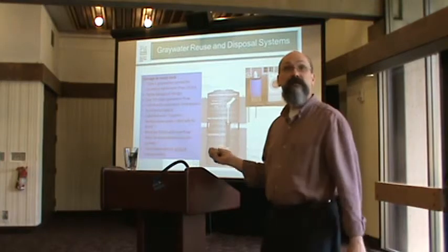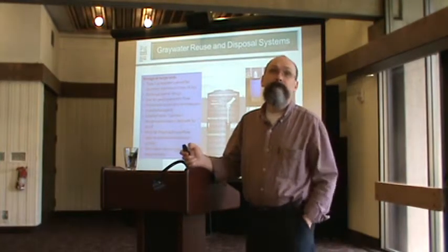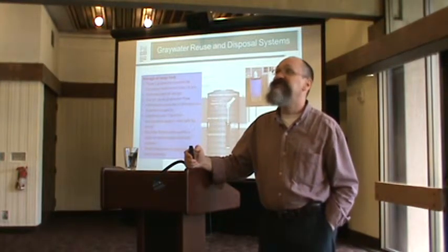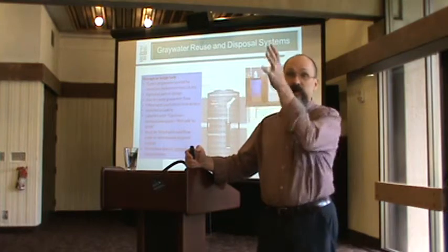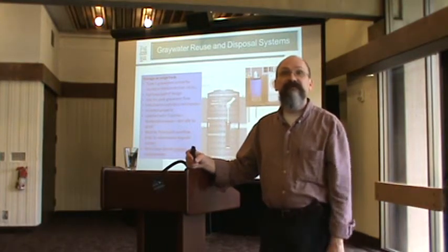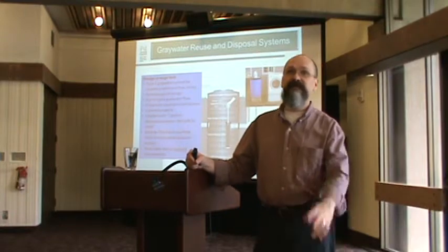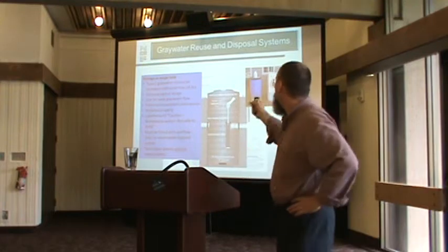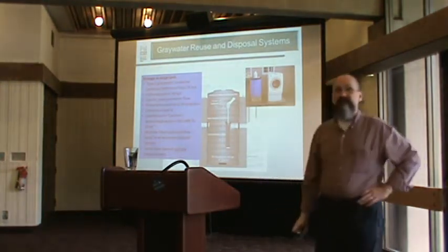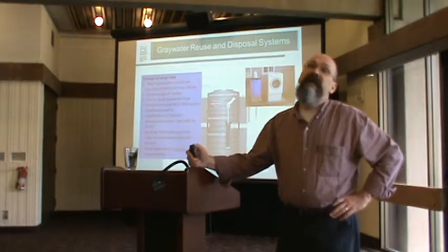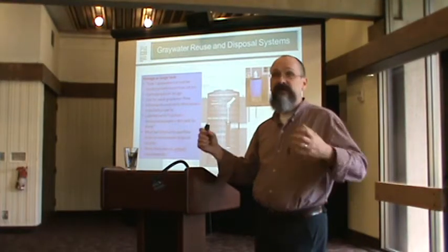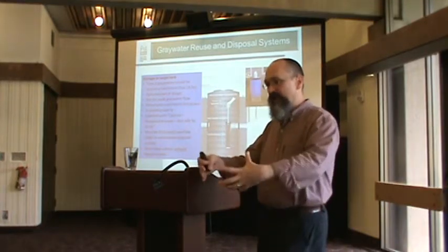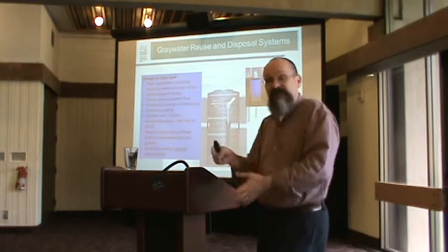And it can't be stored more than 24 hours. How does that tank not store over 24 hours? Well, that's part of what you're going to have to design. These are surge tanks, so the water goes in. I don't know if you'd have a timer that kicks on so that it flushes, making sure it flushes every 24 hours. Or it's just open, with a hose coming directly from it, so it's always draining and it just slows the flow down. That's what a lot of people are probably going to want this for. If you think about your washing machine, it pumps out a lot of water at one period of time. Put it in the barrel, and the hose is going to slow it down.